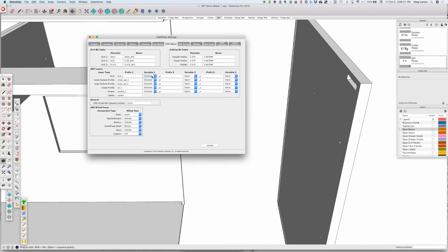These are the defaults that are in there. So we're going to use diameter first, followed by a _D for diameter. We could put any string in there that we wanted, followed by the depth. So the diameter comes from, in drilling's case, the match that was made on the drill table. And then the depth: all holes of the same depth will be put on one layer.